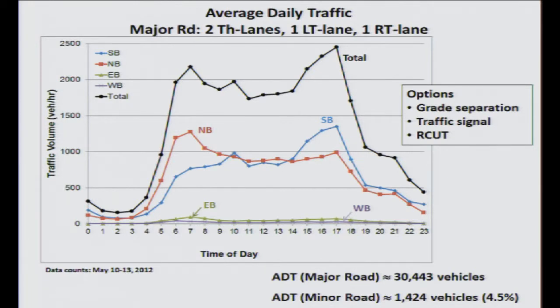But with the traffic signal, you're actually stopping the major road traffic to serve 5% of the minor road traffic. So you have a lot of degradation to the level of service on the major road, okay? And if the volume is not there, it doesn't meet signal warrants, and experience tells us this traffic signal does not give you the safety. You can probably expect more crashes.